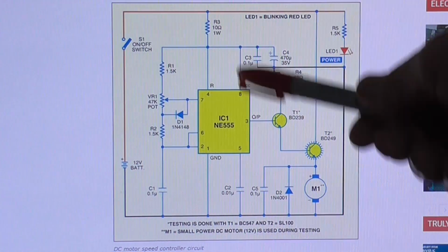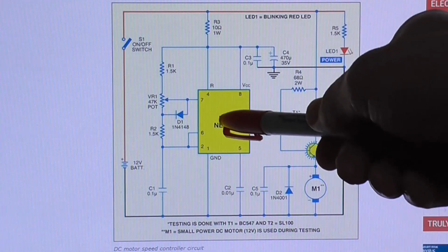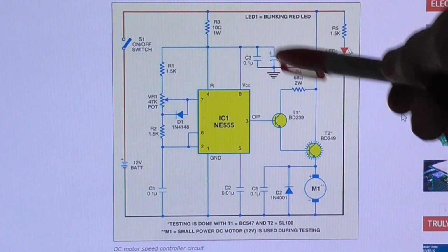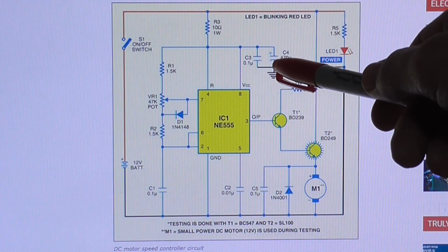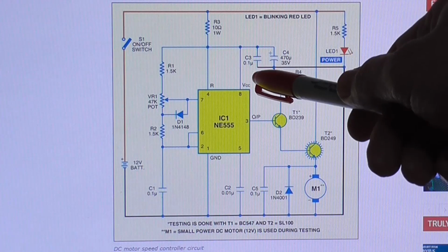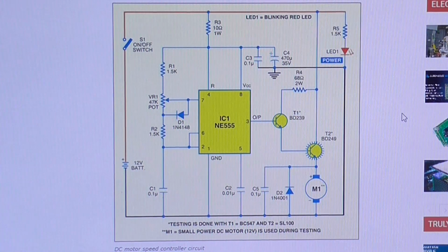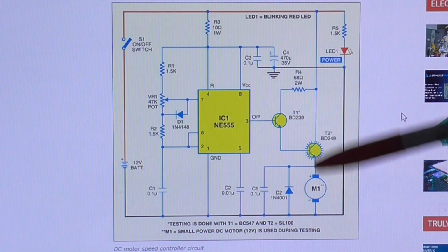It's really irrelevant. They've also got the positive supply rail to the IC DC decoupled through this 10 ohm resistor and this 470 microfarad capacitor and 100 nanofarad capacitor respectively. I believe that's to isolate the oscillator from the output stage over here.